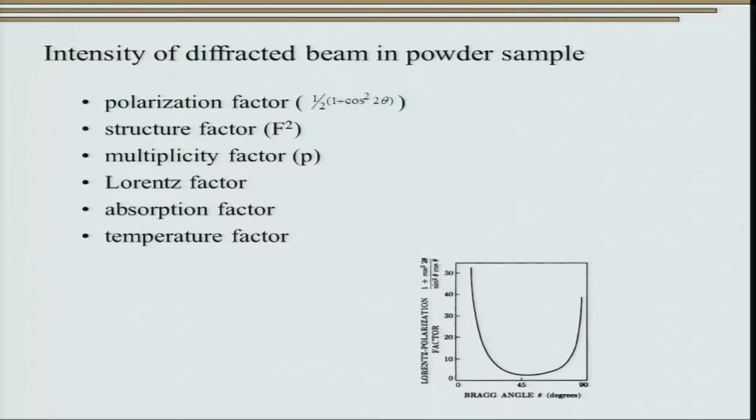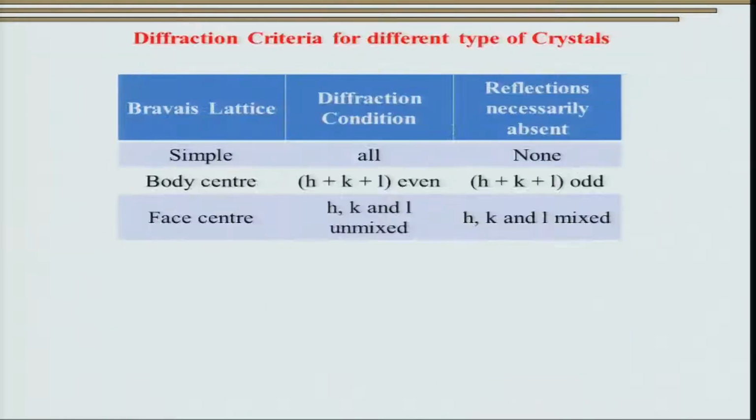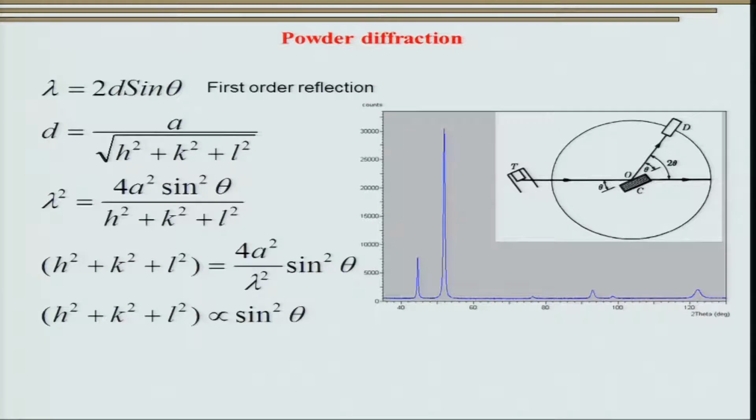Having said that, you must have noticed the intensity of the peaks which I had shown in the earlier slide. Herein, after gaining knowledge about the kind of reflections and the Bravais lattice, I hope you can make a guess that this material showing two peaks very close separated by a third peak and again two peaks close separated by another peak corresponds to an FCC crystal structure with reflections at 3, 4, 8, 11, 12, 16 and corresponding to 111, 200, 220, 113 and so on.